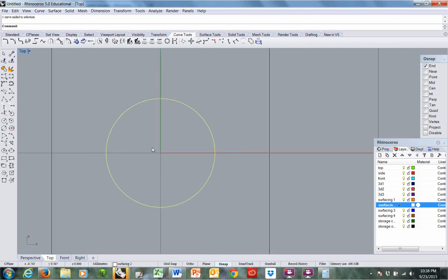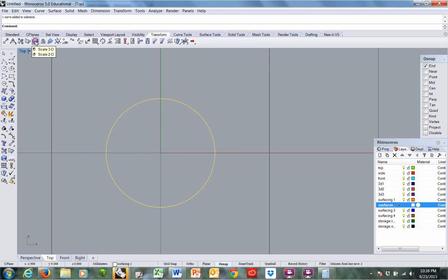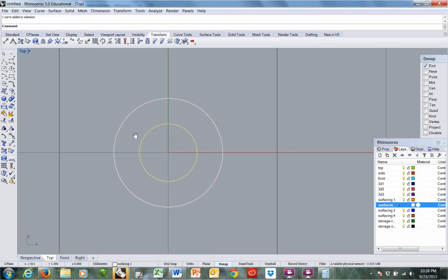The table of a round brilliant cut stone is 53% of its diameter, of its girdle diameter. This is our girdle line. Okay, so to create that, we're going to use a scale command. We want it to make a copy. Origin point, it's still asking for the origin. Type in 0. Type in 0.53. And then we're going to hit escape to end the command, because if we hit enter again, we'll simply keep creating additional copies of this.